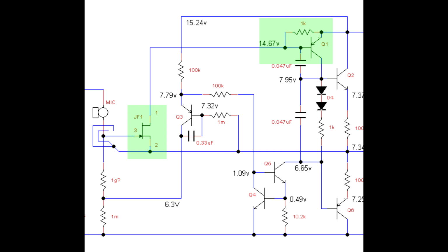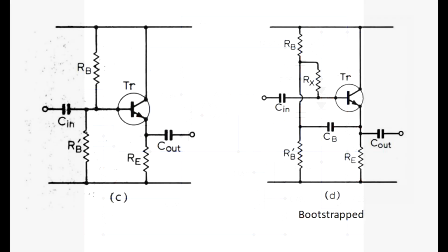Before we take a look at the next part of the circuit, we need to go over a concept. Okay, let's talk about these two circuits here. The one on the left is a standard AC amplifier. So the resistors are used to set up DC biasing of the transistor. The capacitors allow AC signal to flow through the circuit. And so it does a good job of sending this signal through the circuit, and the DC biasing sets up the transistor to operate in its best region.